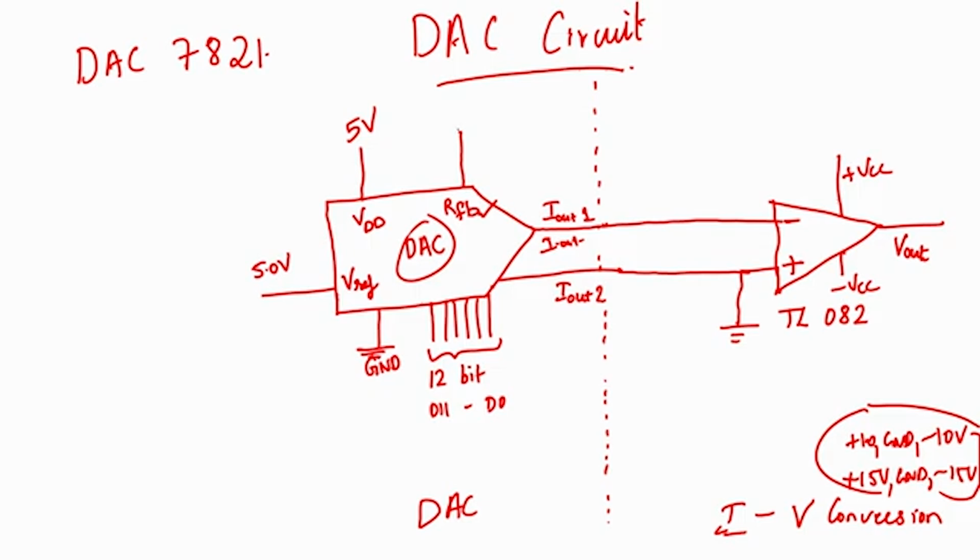So, now our feedback is there. Our feedback now has to go to the output like this. Technically this is all there is for the circuit design to test it out. But because of reference voltage fluctuations, supply voltage fluctuations or output current fluctuations, you observe something in practical circuit design called gain peaking.